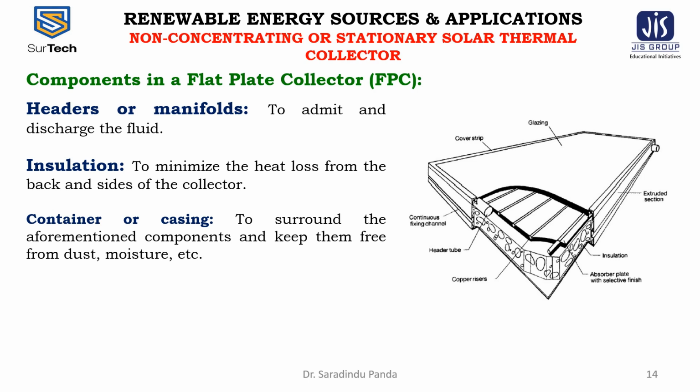To minimize this loss of heat, the bottom and the sides of the flat plate collector are insulated with high temperature rigid foam or aluminium foil insulation as shown in the figure. The insulation material should be dimensionally and chemically stable at high operation temperature. The thickness of the insulator should contribute to the structural rigidity.